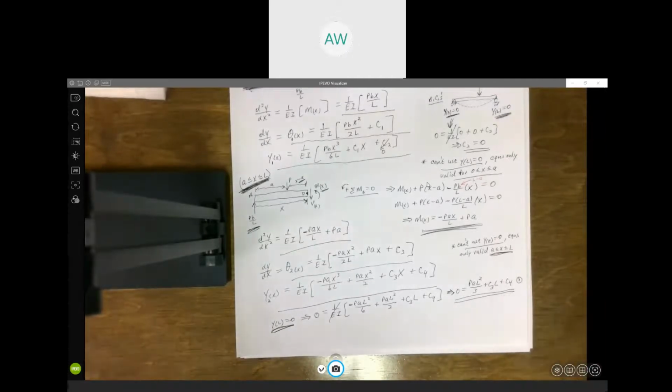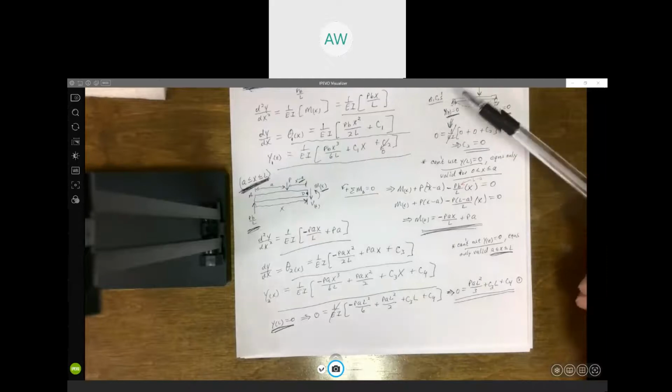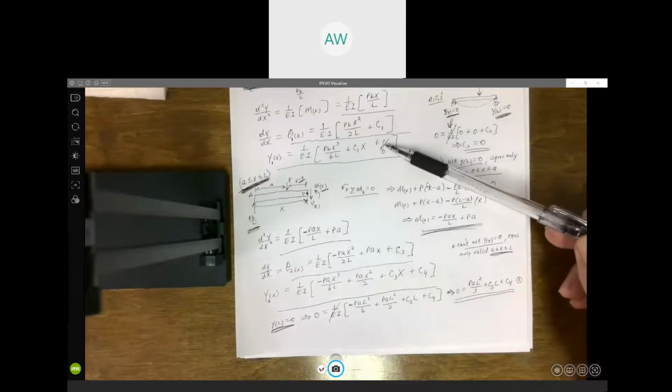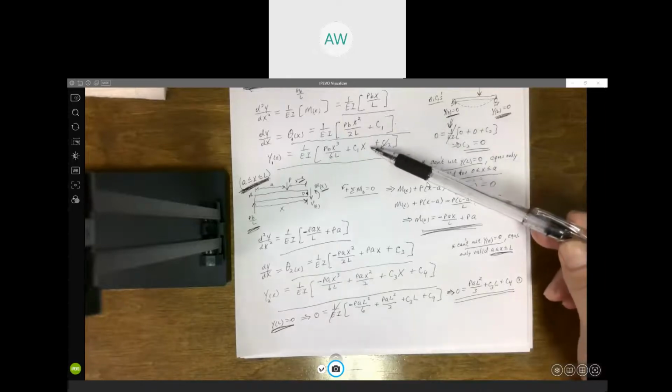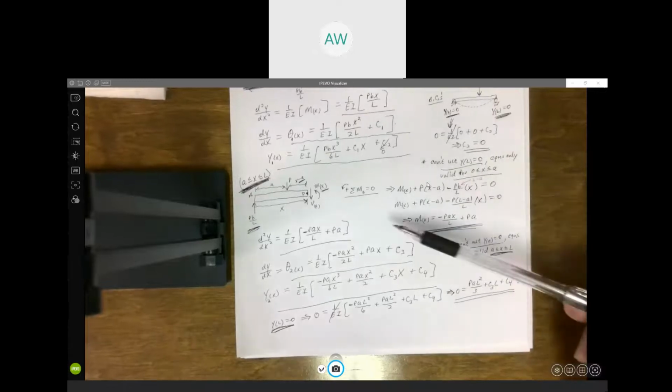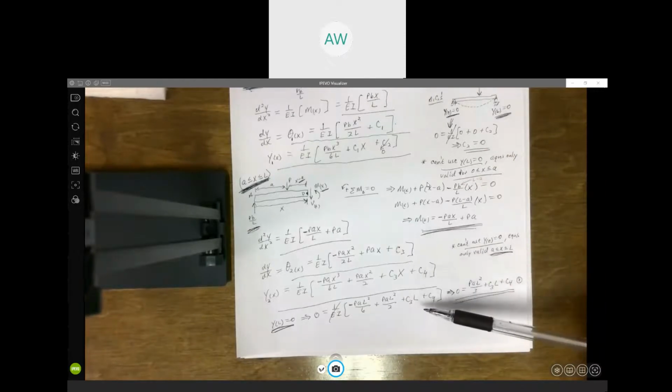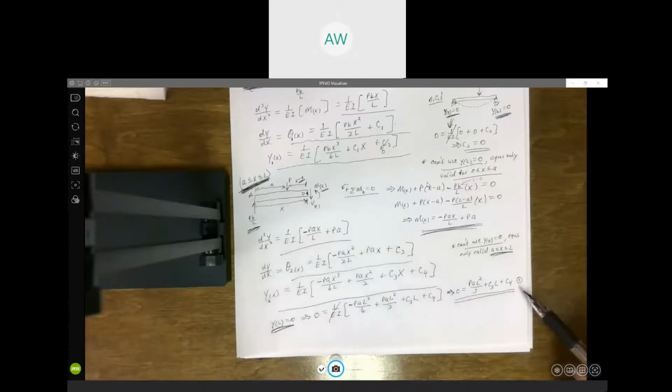And so now here's where, when we started out this nice innocent looking problem, we're running into a situation where I've cut it twice. I got my two moment equations. I've integrated those, and I got my slope and displacement for the first section, but I got an unknown constant, C1. Down here, same thing, integrated, apply my boundary conditions. I still have two unknown constants of integration. So we still got three unknown constants of integration. And at this point, we only have one equation. We can't solve for three unknowns with one equation.